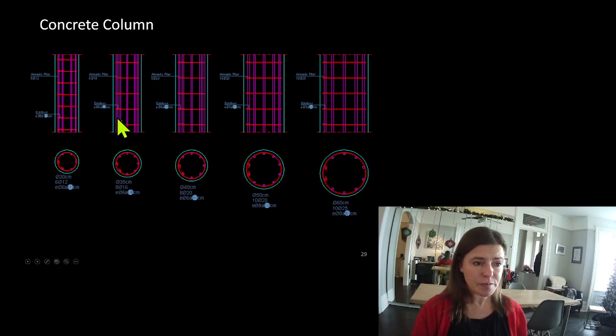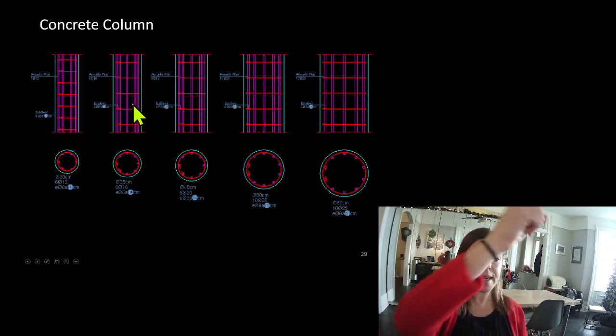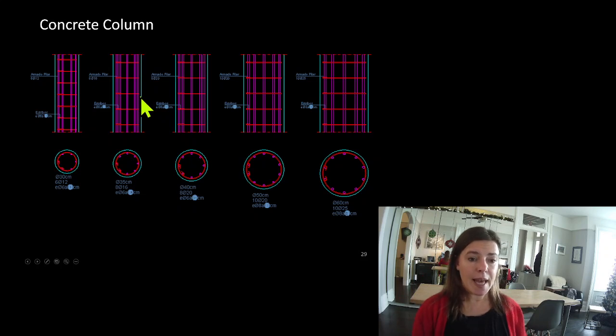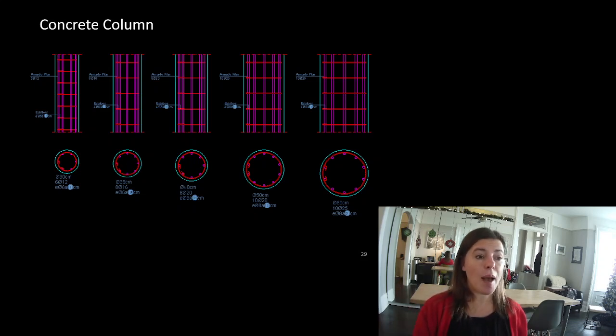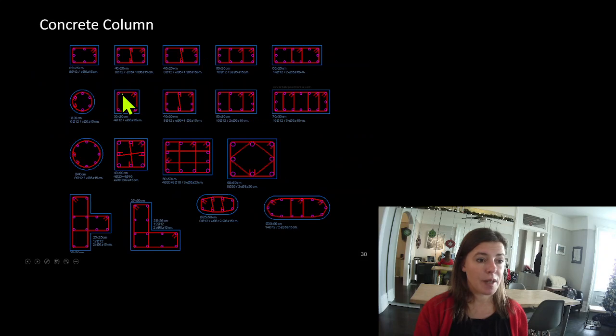The caissons too. So Dave just said that the spiral ties are a little bit harder because they're continuous now, right? You've got to keep going with them. This is nice that you come on site with this thing and you kind of bend it around and tie it off. So they tend to like this because they can assemble it a little bit easier. But those spiral ties are good for high seismic zones. I'm guessing it's the way it deals with the ductility and how it spreads out the load through the element. So Ottawa is a surprisingly high seismic zone.